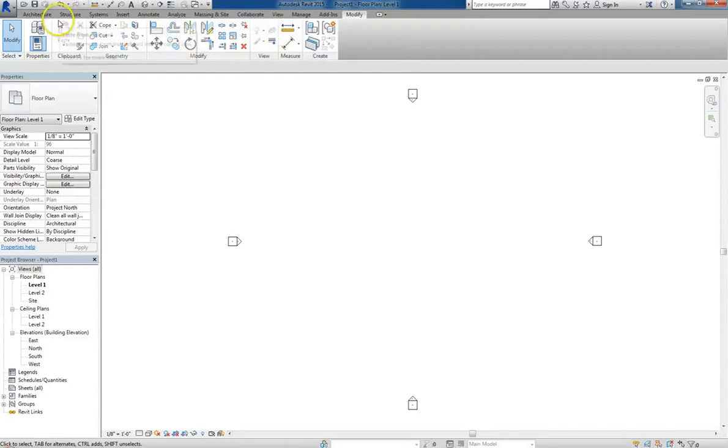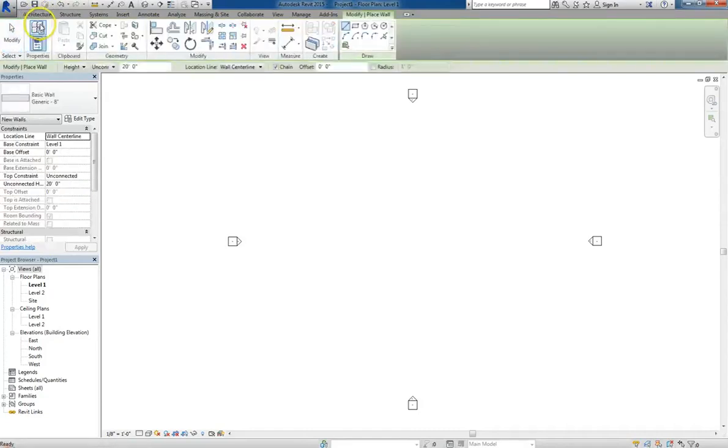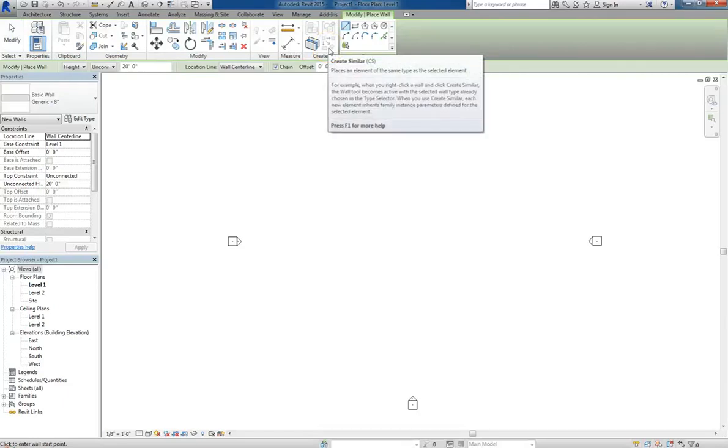To get started on this, let's just build a simple wall. So click on the Architecture tab, and we'll select just a generic wall. Same one you've seen before, 8 inches long. Now you'll notice that the Modify tab pops up right away. That means that anytime you click to add something, floor, ceiling, wall, whatever, you're going to be able to use the Modify functions to impact it.